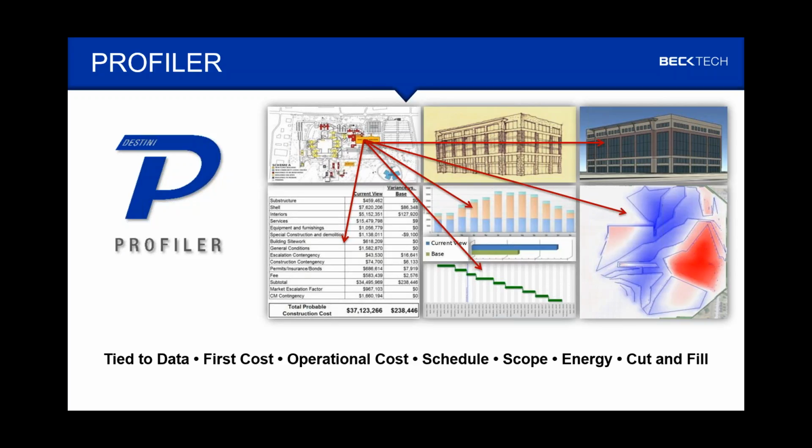So if it comes up with the project requires 300 tons of cooling, you can apply $5,000 per ton, or you can define specific line items, a chiller, a pump, an air handling unit, to match those tonnage requirements. More than that, it also will run an energy simulation over a period of time to give you feedback on what is the operating cost for that particular configuration of the project. If you rotate the building, rerun the analysis, it will show you the delta.